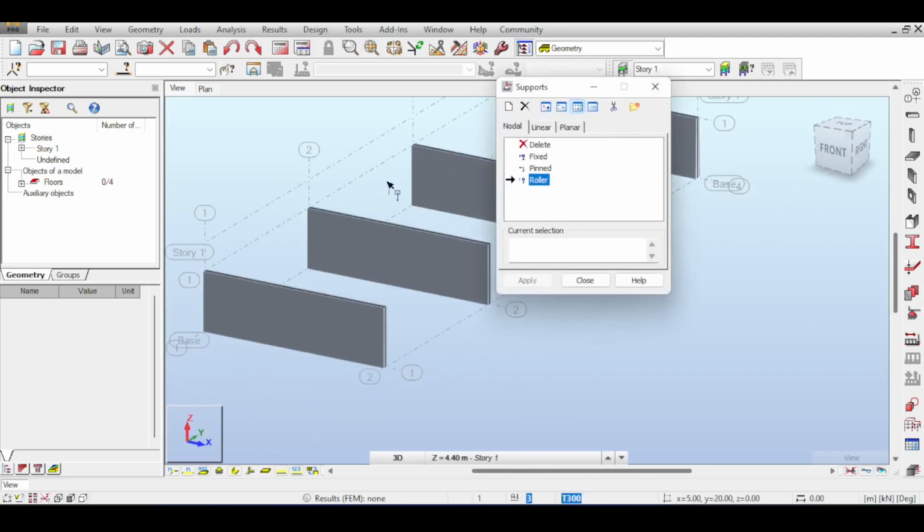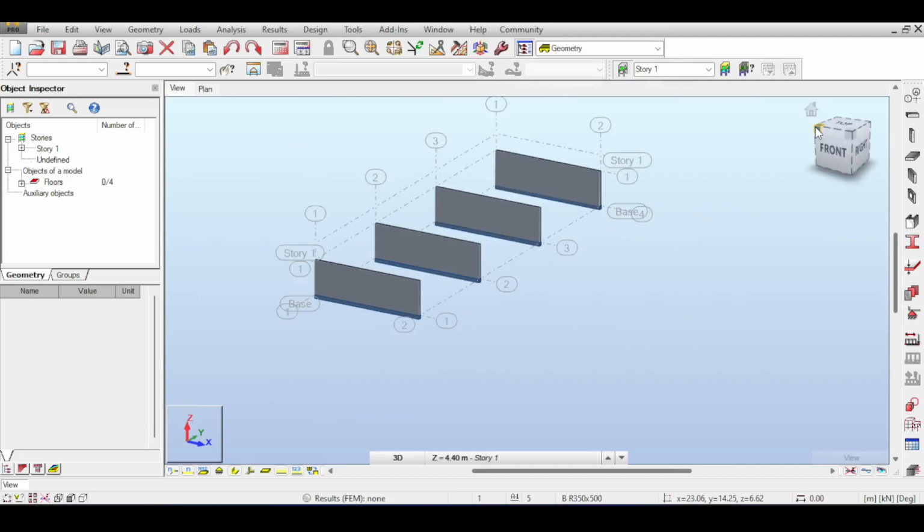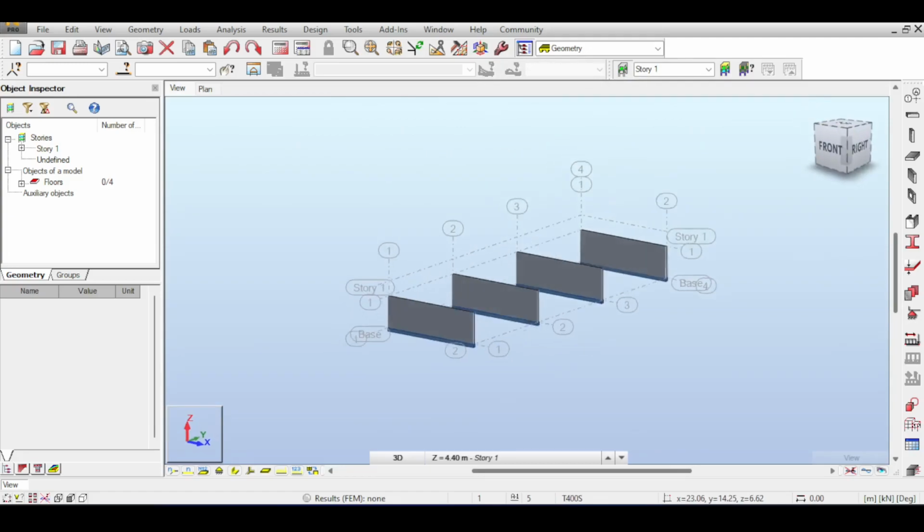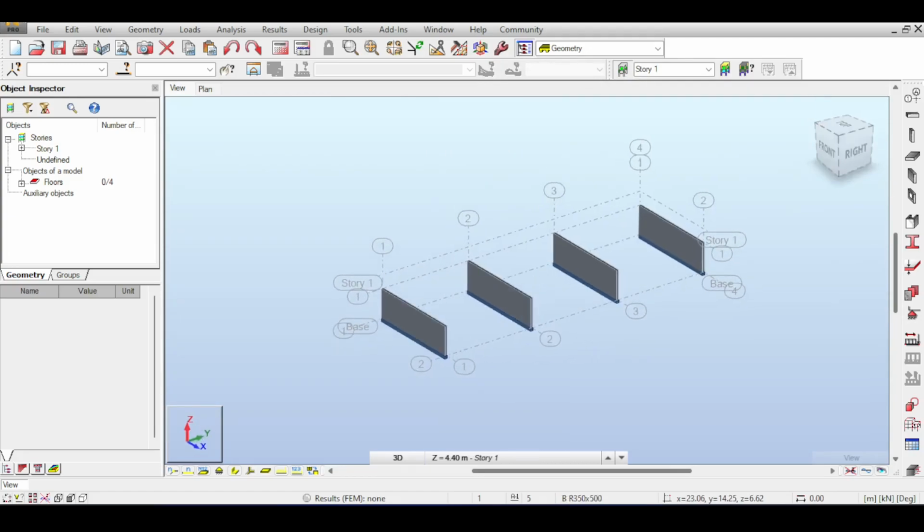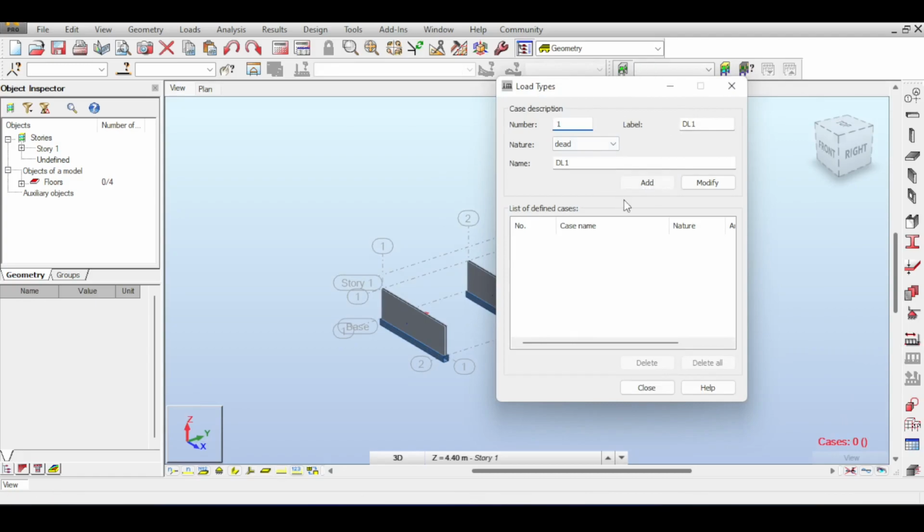So first of all, I'll just click on support, click on fixed, fantastic. All right, so I have fixed my walls, and now of course I can apply my earth pressure again. Now I'm really fast here because I have explained this before. So I just go to define my dead load for reasons explained before. Now I had a nice comment from our dear subscriber Sarpei talking about the British code, which applies a live load, a predetermined live load on the retaining walls.